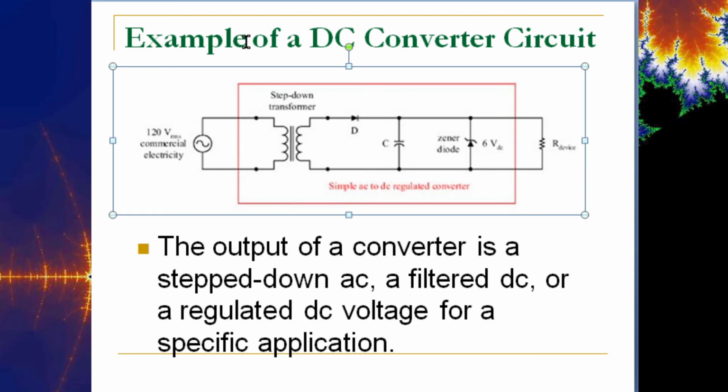And so now you've got positive hump, positive hump, positive hump. Add some other massaging circuitry in there, like capacitors, to reduce that ripple from when it goes from hump down to 0, back up to the peak, down to 0. If you're following my cursor, you would just go to here, and then before it goes all the way down to 0, it's already being charged to the next one.